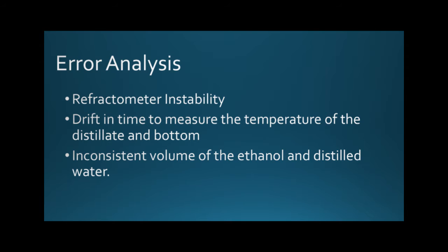We should also look out for time discrepancies between recording values for the distillate and bottoms. There needs to be a vigilant timekeeper that sets the timer and notifies everybody to collect the samples and record the results when the time comes. The volume of ethanol and distilled water should be measured accurately so as to not obtain faulty data. The mixture must also be mixed properly when measuring the volume of samples or distilled water or ethanol. The eyes have to be perpendicular to the scale so as to record reliable data.